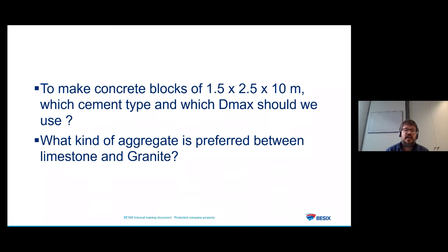In this case, I didn't mention durability, but these blocks are non-reinforced. But we still need to be careful with the attack of the sulfates, because this is on the concrete itself. So it is correct, but in this case, the fly ash is not absolutely necessary, because it's a block, not something that we have to pump at high rise or over a long distance. So at this moment, the GGBS will not be a big issue in terms of workability. But your point is totally correct. If we need to pump a little bit further, a few hundred meters, then it might be necessary. But in this case, it's something that you can cast directly.